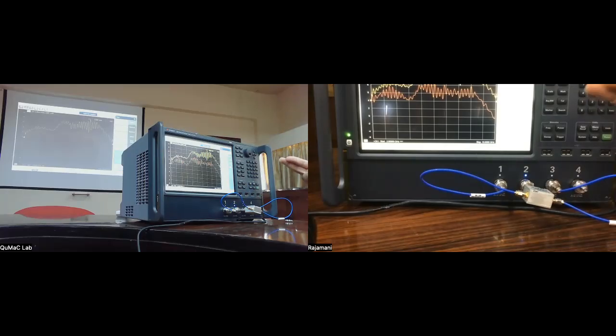But this is important to know because this is what will allow this feature to happen. Because these two come out in phase, then they will re-enter in phase. And that's why most of it will come out of the sum port. Because if they are in the same phase, the difference will be close to 0. The sum will be double the value of the individual. Okay.